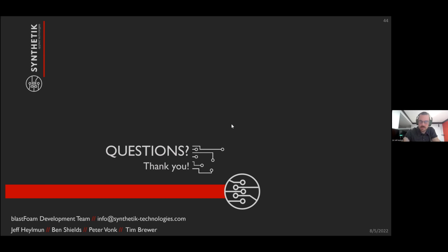Yeah, this is much more along the lines of a VOF type simulation, though it's not quite that. It has shared velocity and temperature, so we don't have any drag or anything like that. It's just a mixture velocity, so it's just volume fraction. We don't use Euler-Lagrange, but we do have the option to include it, so if you want to do Lagrangian particles, you can do that. We also have an Euler solver in BlastFoam. But those are both quite different than what we typically solve.